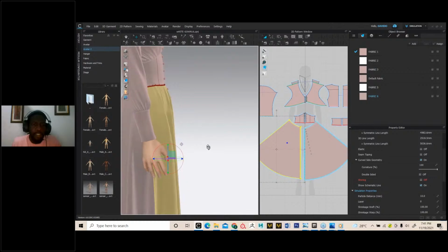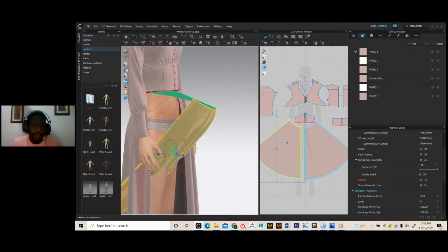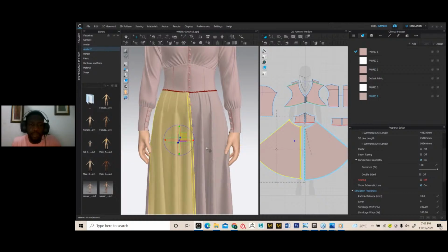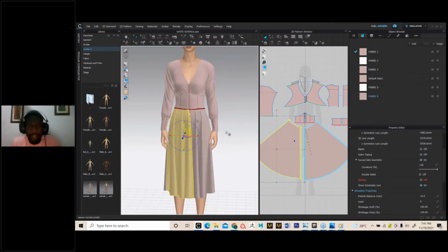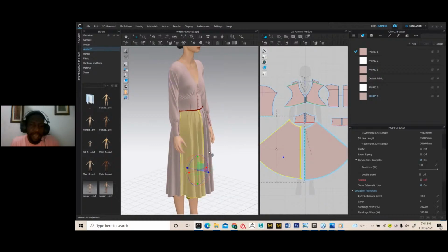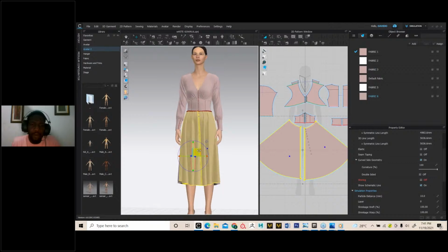You can also rotate with the gizmo tool. You can turn your sketch like this. So it's very important you know how to use the gizmo tool. It's not difficult to use, because when you create clothes in this space and they appear in your 3D space, sometimes you are going to be the one to offset the pattern. Sometimes you might create some clothes in this place and for some reason you find the clothes in another place.